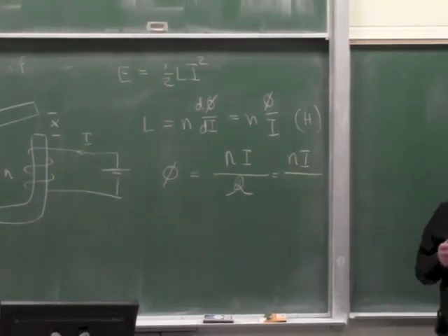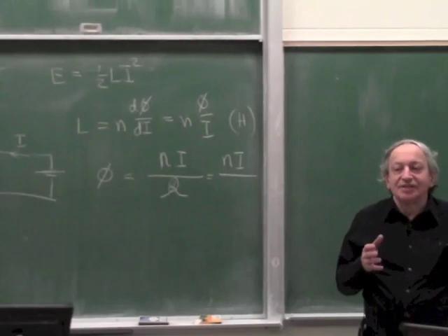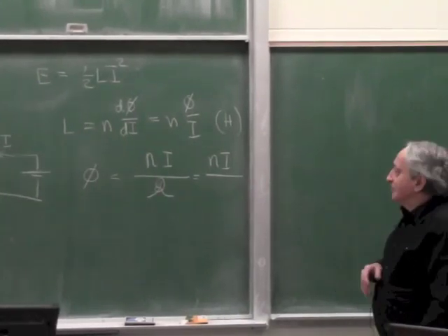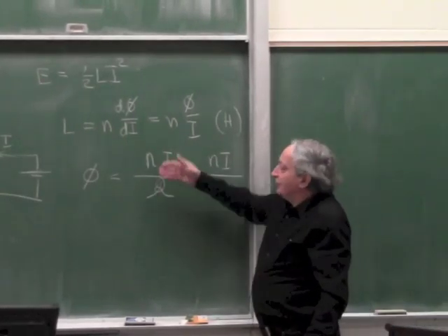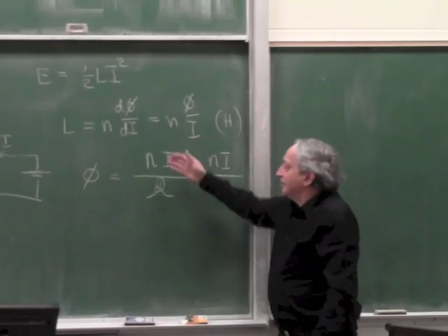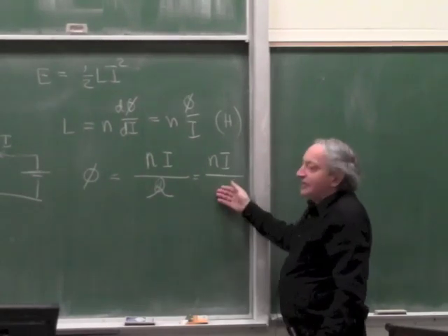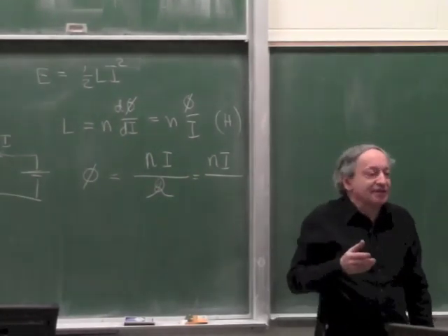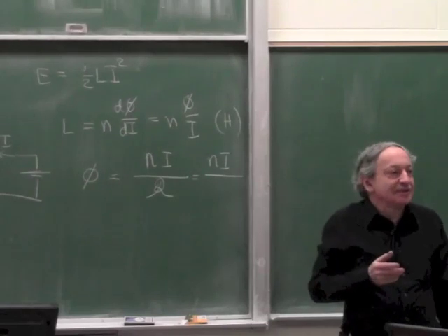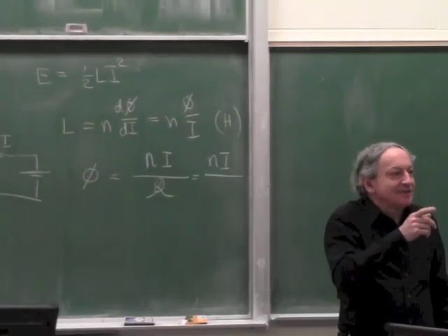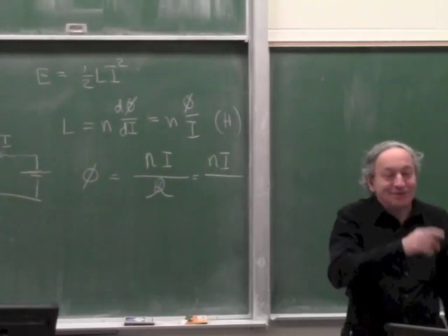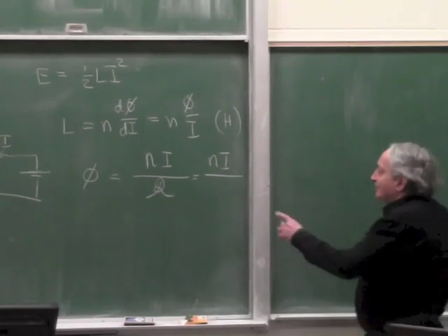What is the formula of reluctance? It's very similar to Ohm's law. In Ohm's law the current is V over R. Here it's Ni over reluctance. So what is the formula for reluctance of a magnetic circuit? Length over mu naught times mu times A. Good, very nice. Okay, so the same as Ohm's law.